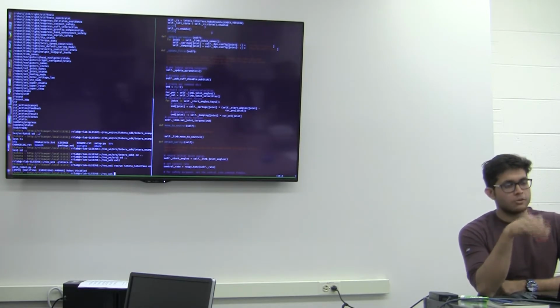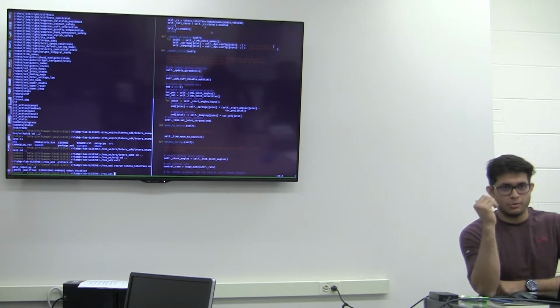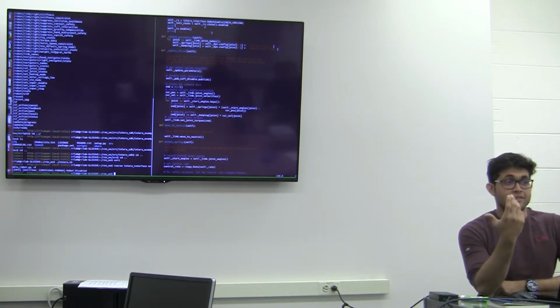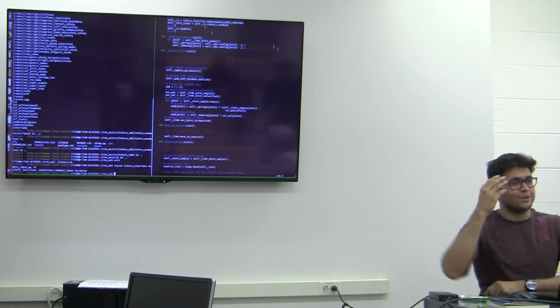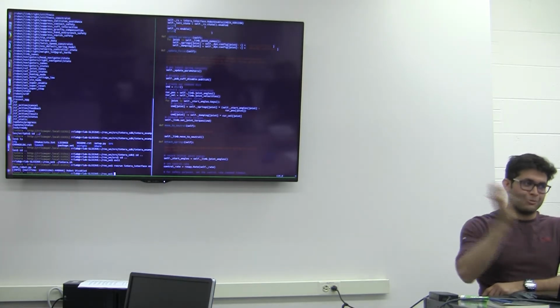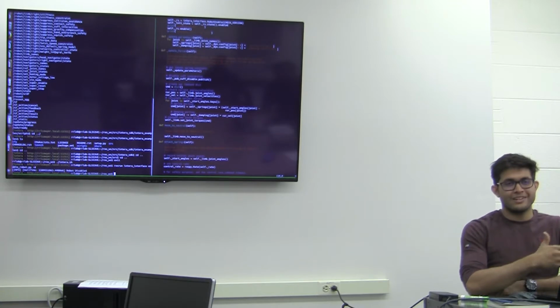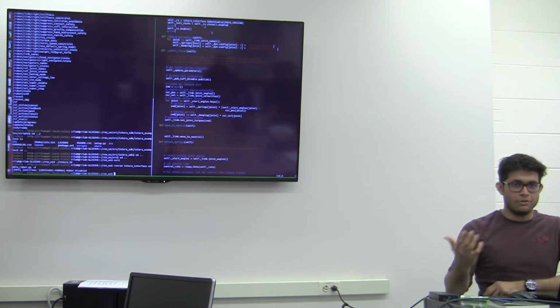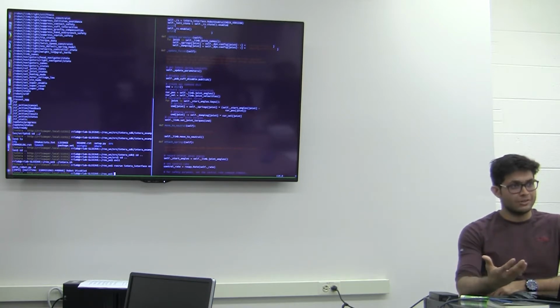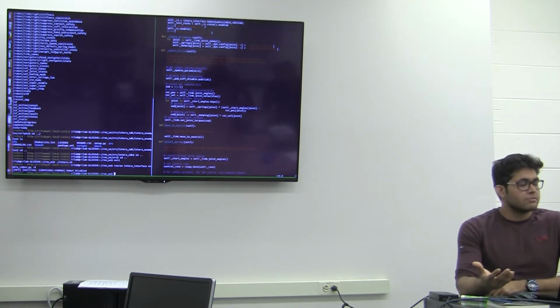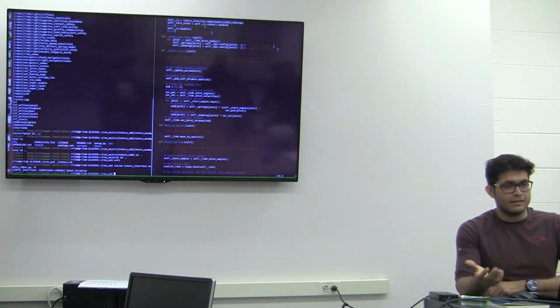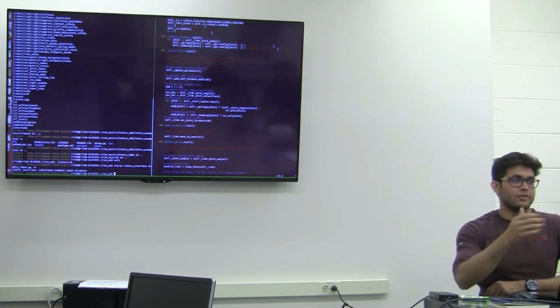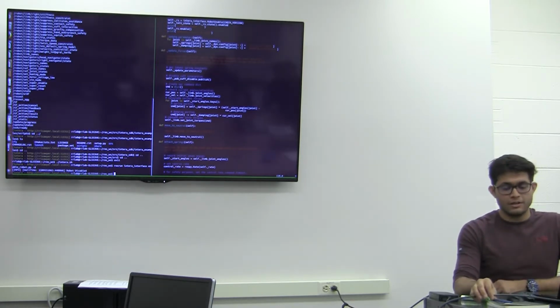For collision within the robot itself, it uses the URDF collision tag. Go through it, read the URDF, it's very interesting. It will change your perspective from SolidWorks to how robots are modeled in software. It's the same thing, but it will change your perspective on how robots are really modeled. DH parameters, you're reading through it, right? URDF will give you a much more detailed view of why you need those DH parameters. You'll figure it out once you start working on URDF.